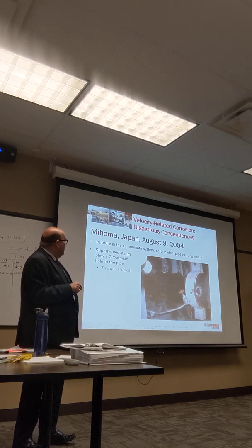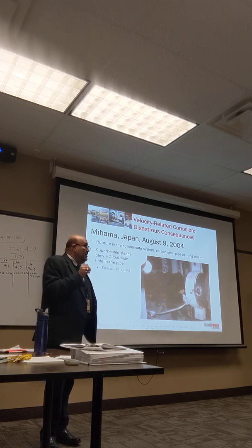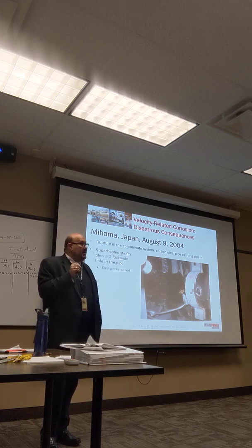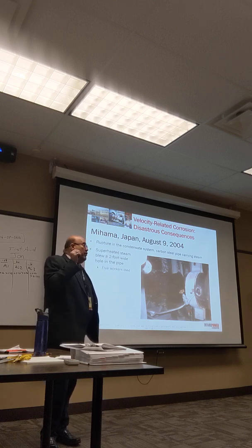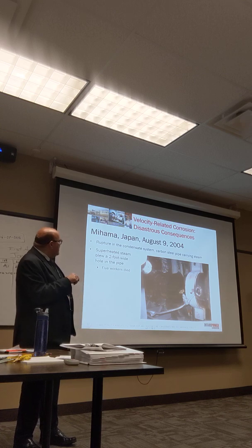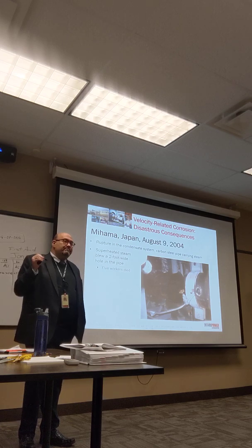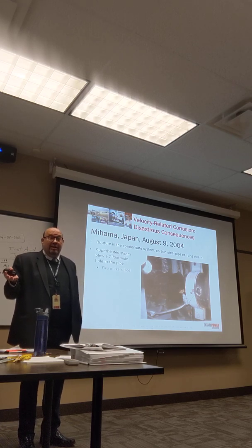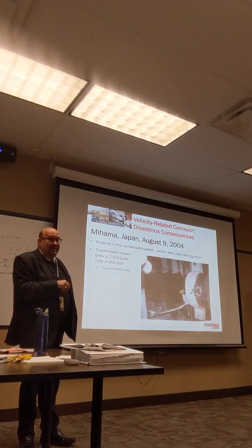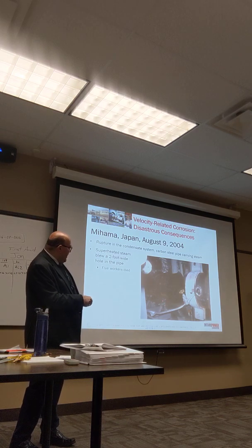And since the 70s or the 80s, there was a PM to actually inspect. And the Japanese company did not inspect that one for years and years until it failed, when I think it was 1.5 millimeters. All of this you can find if you Google it, you'll get the report. So it's lost a lot, technically all its thickness, and workers were standing there. And when this ruptured, you can see the pipe opened up.